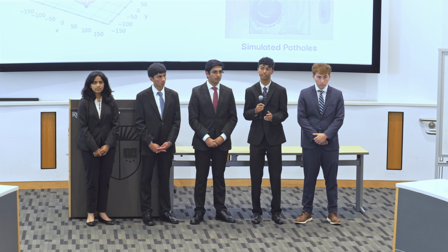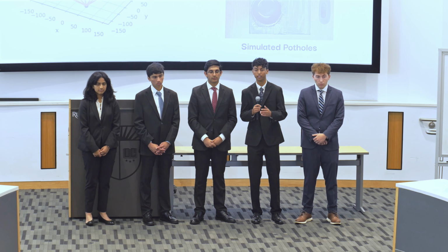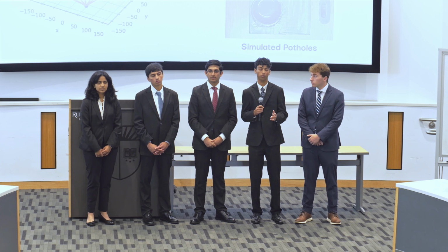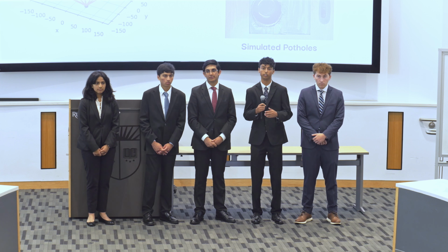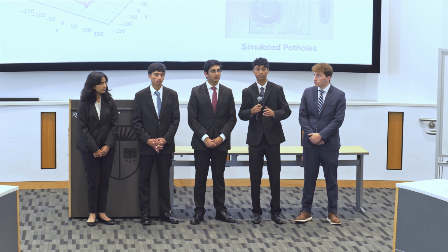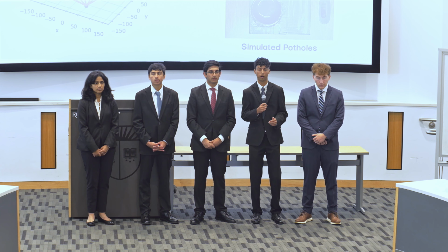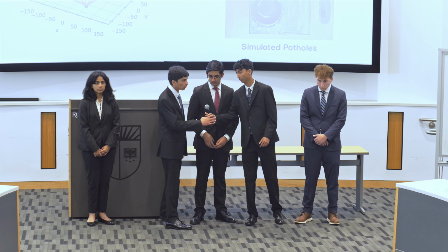To test the viability of these algorithms, we conducted over 150 trials with simulated potholes of small, medium, and large size depicted on the slideshow, alongside different parameters for our LiDAR instance angle mount and our slope deviation threshold. This involved mounting our LiDAR module at 9 inches high and gently pushing it to capture the entire scope of the pothole. Here I will hand it off to Rahul to discuss the volume aspect of this project.